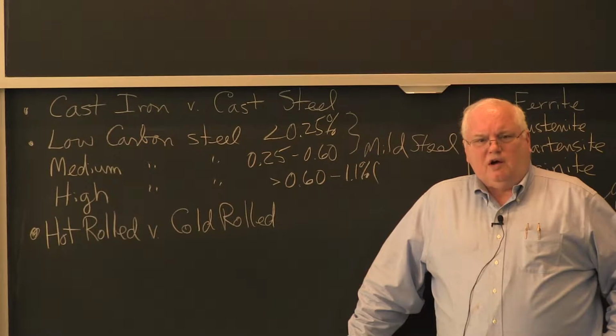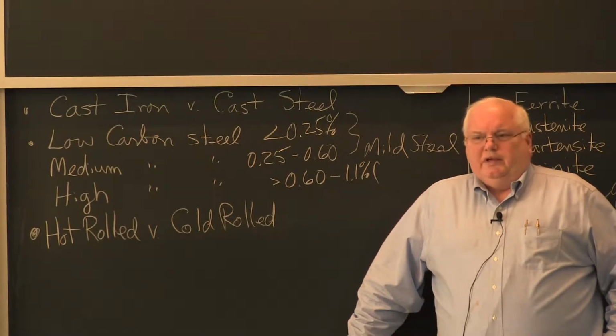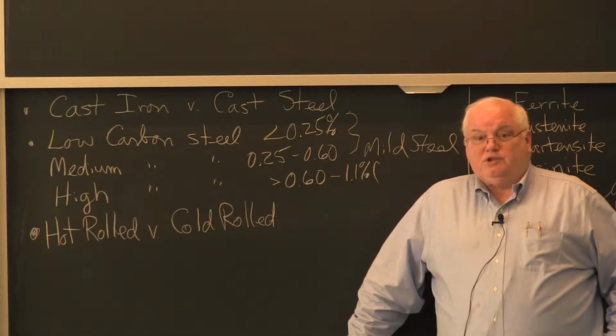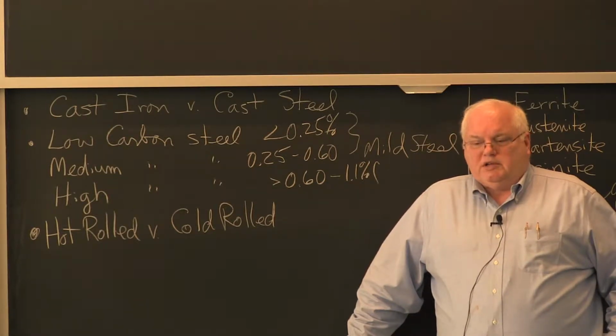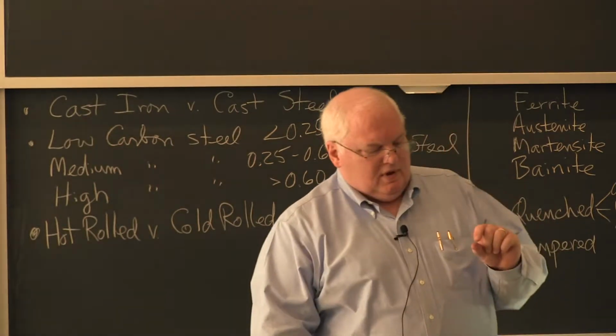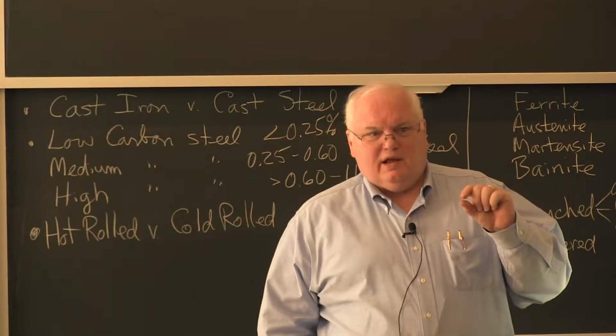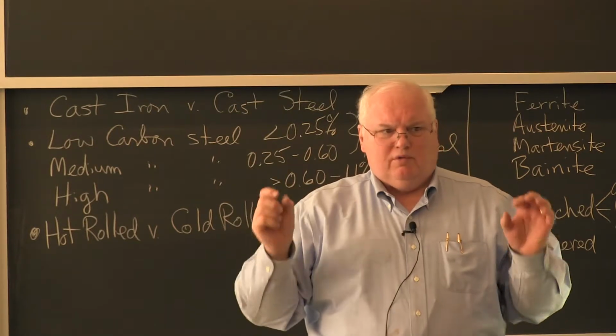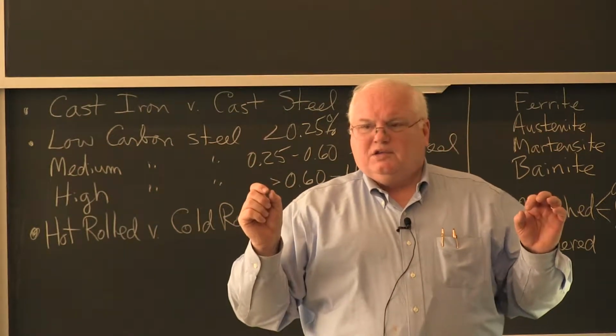Someone else mentioned hot rolled versus cold rolled. And so sometimes you say, well, I have a piece of cold rolled steel. Well, what does that mean? Well, it means it came from a particular mill that can take hot rolled band, they call it, which is just a great big roll of like 1/4 inch thick steel.